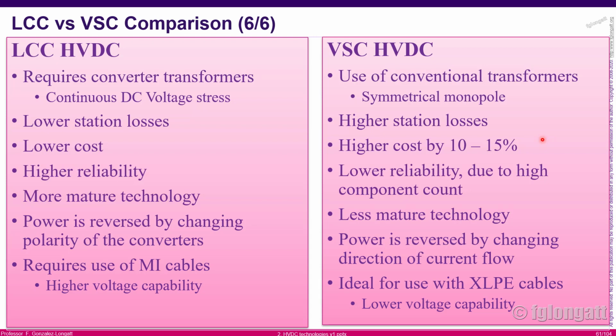Main difference: LCC is still low cost, high reliability, and is one of the oldest technologies. As a consequence, it is a mature technology. However, the VSC has several problems. The GTO and the IGBT, because they can commutate when you say close and open, there are some losses related with those devices, and those losses can be extremely high, okay?